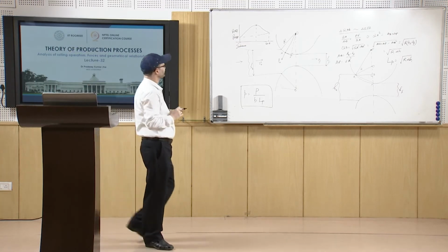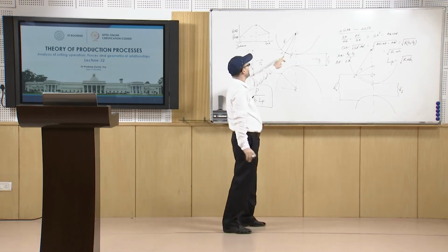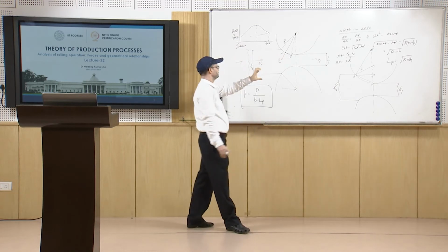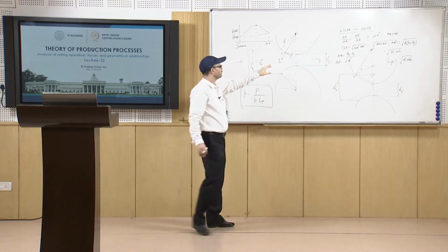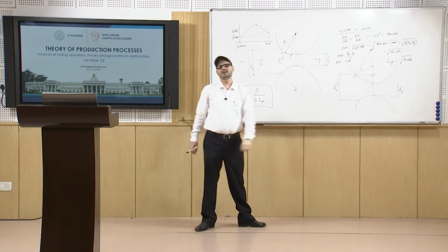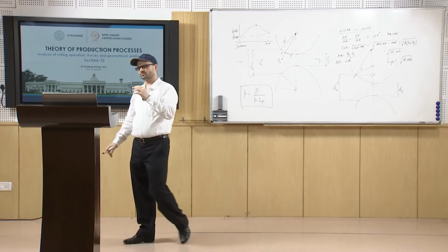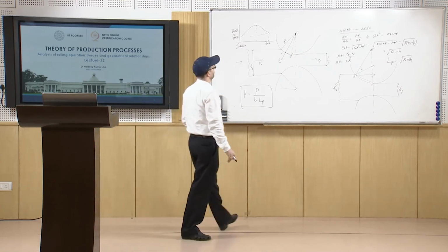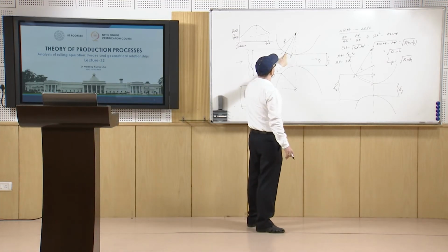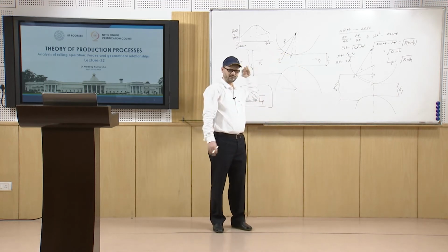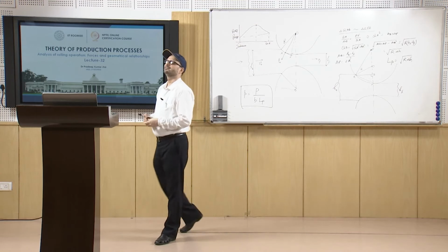Further, we discussed that you have two kinds of forces. One force will have the effect of not allowing the strip to go in. The other is the component of the frictional force, the tangential force, whose component in the x direction will try to pull the strip inside the rolls.